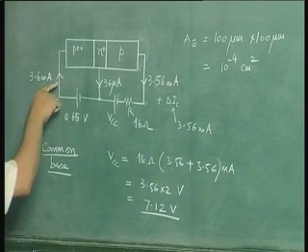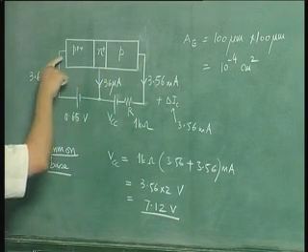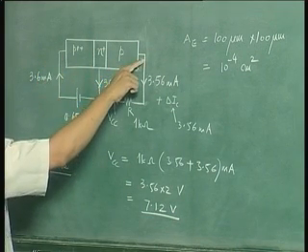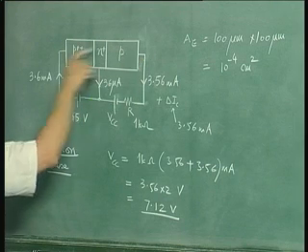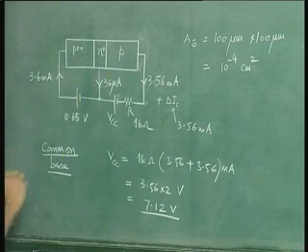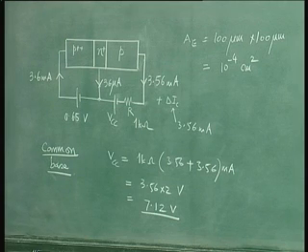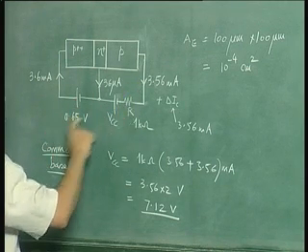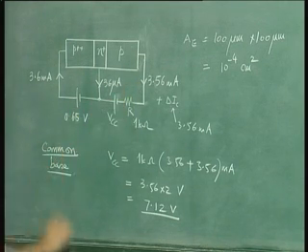For example, here the collector current is alpha times the emitter current. Actually there is a slight fall in the output current as compared to the input current. This is input, this is output. So you are not really having a current gain, you are having a current loss. You are however having a voltage gain that we have seen, or a transconductance gain.